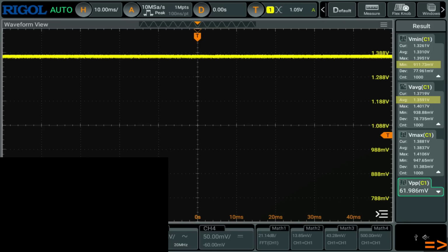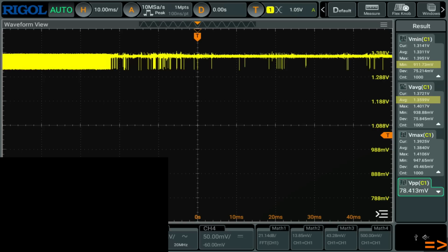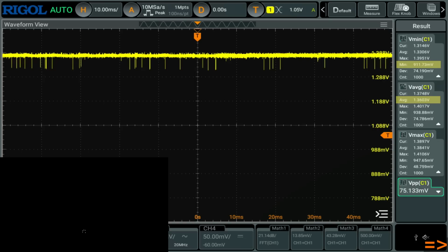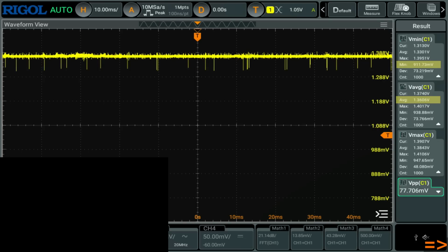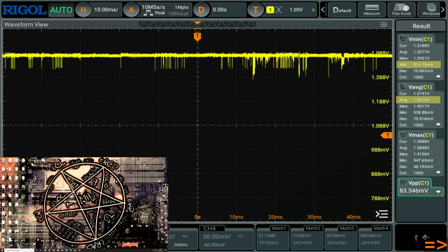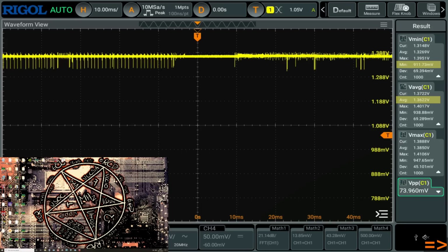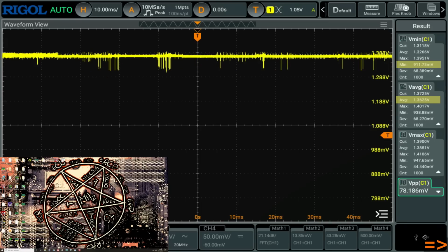Yeah, because now we're going to start seeing idle... You can start seeing that there are upward voltage spikes at idle now. Because basically what the load line saturation setting does is, when you're below the saturation point, you have no V-droop. So below 120 amps, we're basically on like mode 1 LLC.